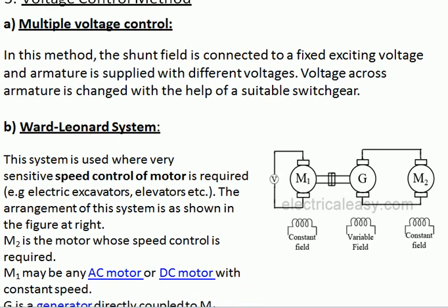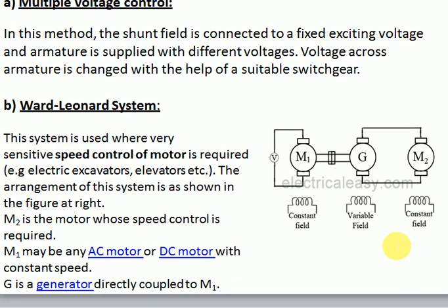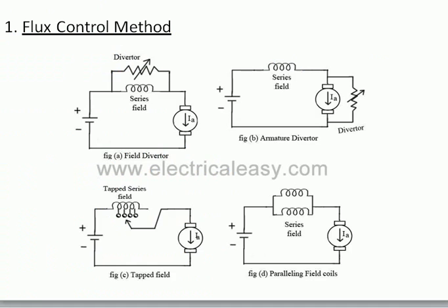What we are going to do in this case is control the energy given to this motor. If we want to control motor 2, this is an MG set, motor generator set, so the energy it gets will be generated by the generator. The generator will generate energy according to the mechanical energy it gets from here, so we control that mechanical energy itself. This system is very expensive and in general applications it is not used, so only in specific applications can we use it.